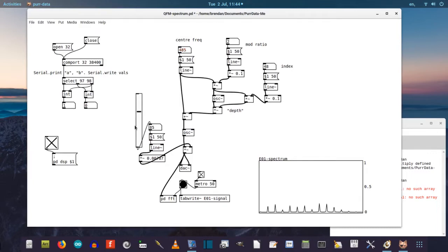And this is because when Chowning first invented FM synthesis, the main goal was computationally inexpensive recreation of acoustic instruments. And in acoustic instruments, we see this behavior that as pitch rises, brightness increases somewhat. So as we raise the center frequency, the index rises as well.